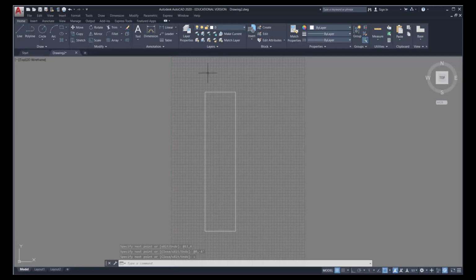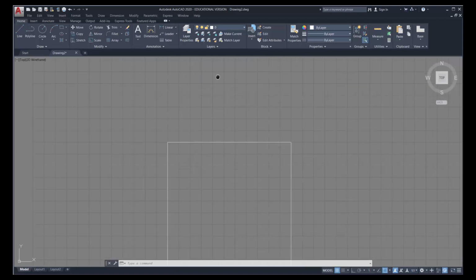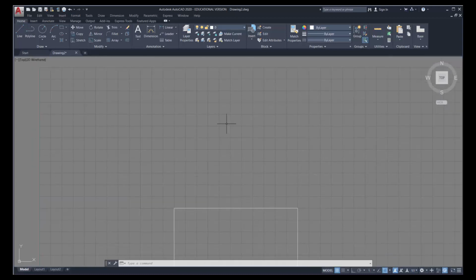And now I'm going to pick up a point at the top, and we're going to draw an object near the top of it. But the object is fairly small. You can see there's very little grid paper left. So I'm going to roll my mouse, and I'm going to pan it so I can see the top of the grid area, and I'm going to focus my attention here. So this kind of recaps our zoom command. I'm going to click on line, and I'm going to pick up this corner right here. And I know that I've got it when I see that green box. That's my snap endpoint, so I'm going to click on that.